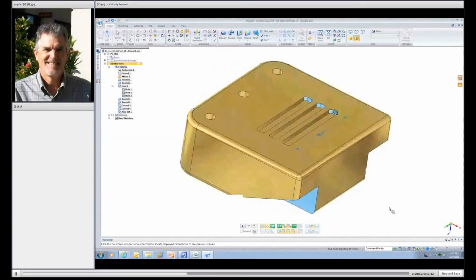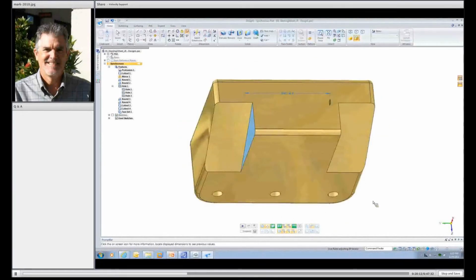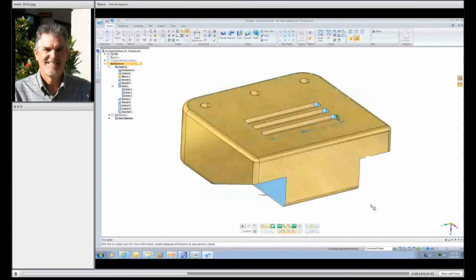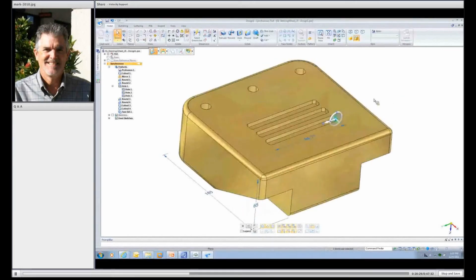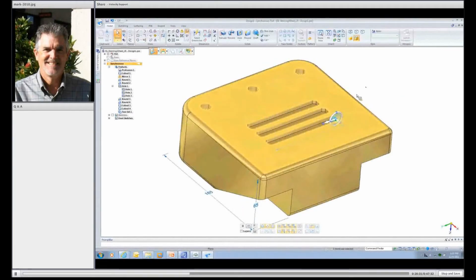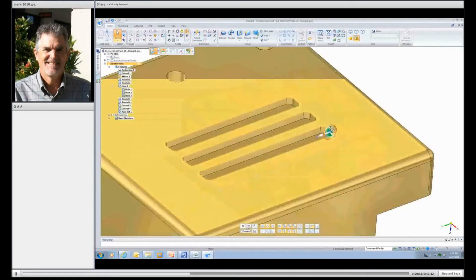In order to do that, Live Rules also has shortcut keys. You'll notice pause or restore is an R, the letter R on your keyboard. If I want to make a change to what we call advanced live rules, I can do a Control E, and what it does is it brings up a dialog and highlights all the faces that are being manipulated.